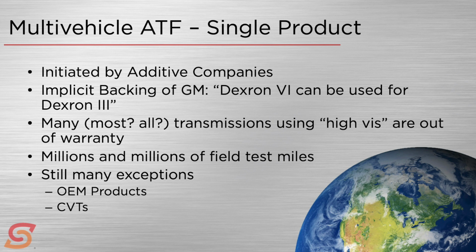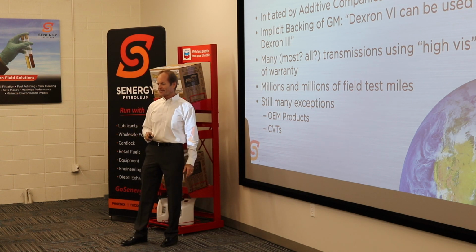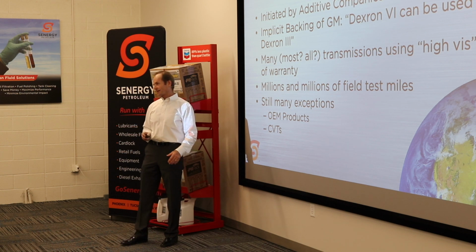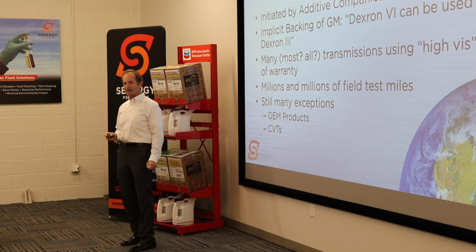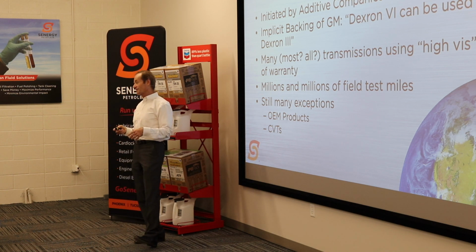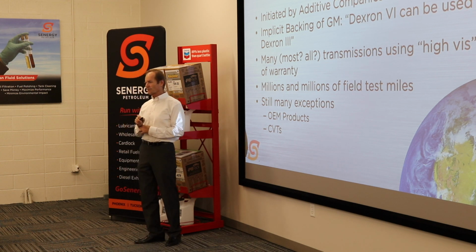Maybe someday someone will have an even more universal ATF that covers it all, but definitely not any CVTs. Well, I already said not any, and that would be a lie, because there are some low power rubber-based CVTs that can use certain regular transmission fluids, but those are kind of rare.